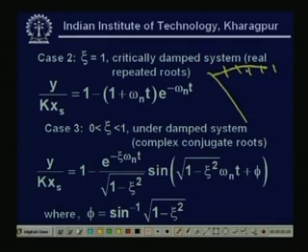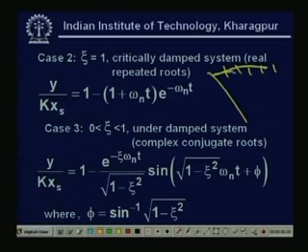That means that is where I will take the measurement. If you take the reading whenever it is crossing, you will be wrong, because that is overshoot. When it comes back to the original position, that is the actual reading, because we have done the overshoot purposefully due to the spring and all these things. It is an underdamped system and the value of the damping coefficient is 0.6 to 0.7.